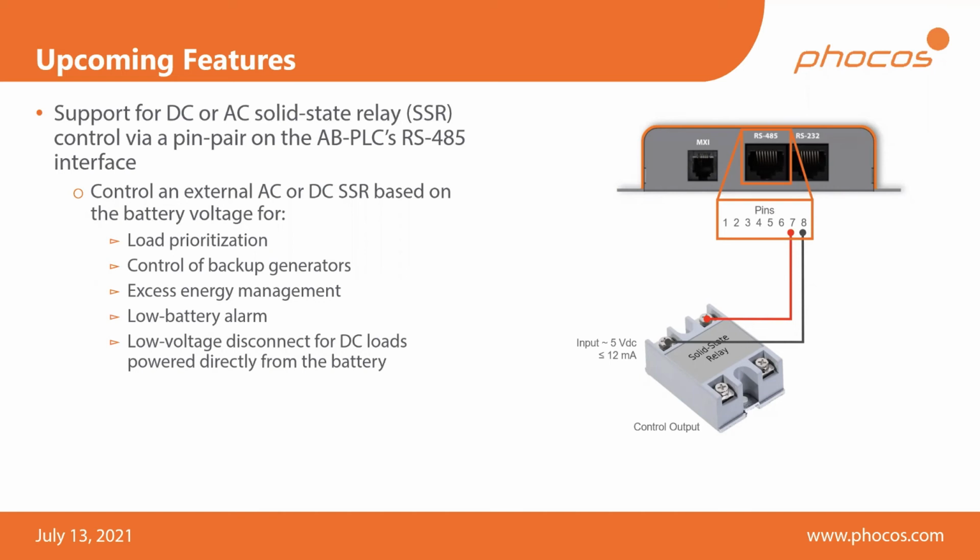In other words, you might have a pool or something that you want to heat up, or just the warm water in your home. You can put a heater inside your warm water reservoir, and that heater will be turned on automatically when you have excess energy. So instead of wasting that power that your PV array is producing, you can still use it to heat something up, or just to run very non-essential loads which would otherwise remain off.